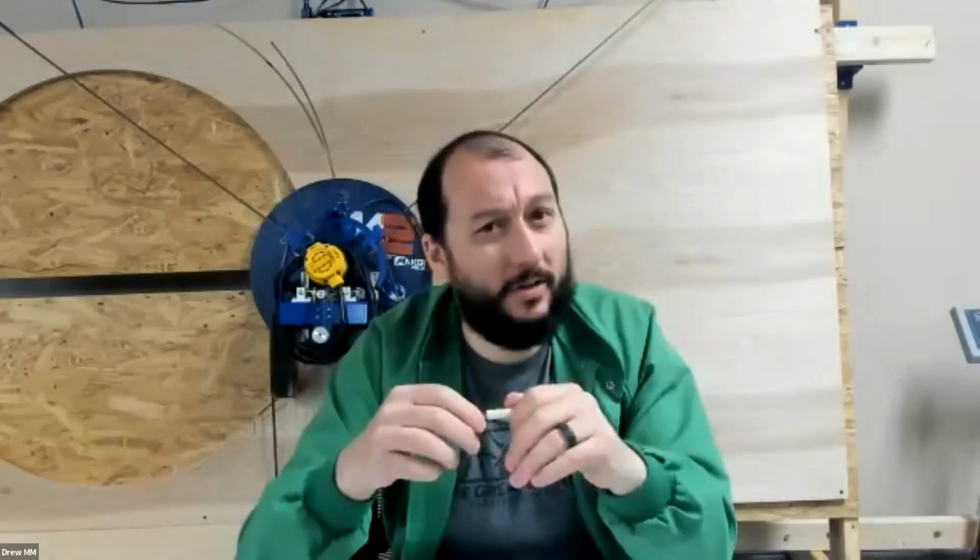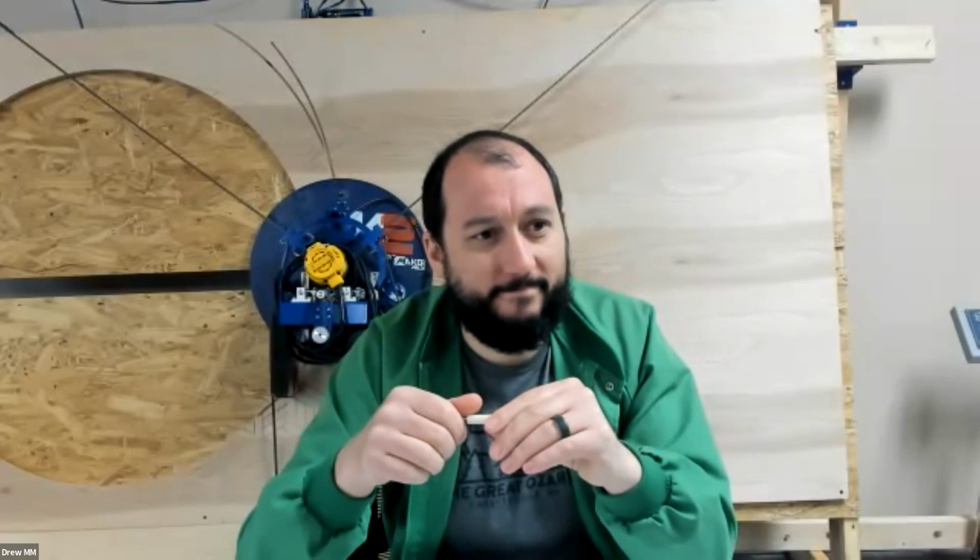So it's not like a MakerBot. We have a couple of the Method X's, and even that's MakerBot's next level up printer too. So yeah, it's a different system for sure. Most of the small ones need a dual geared extruder, or a dual extruder, to be able to do that and have two nozzles. Like the Raise3D does it really well. It moves the nozzles up and down when it moves around, and it can print out of those different materials. But ours is just a single extruder. Right out of the box, it can print out of flexible TPU, PETG, and PLA.